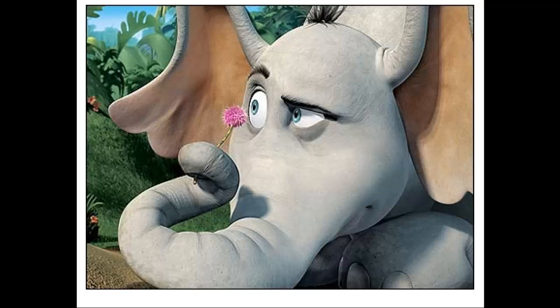And when I talk about scales, I'm talking about the physical rulers, the three-sided scales that are set up for engineering and architectural and mechanical drafting, so that if it says 1/4 inch equals 1 foot, we have a scale, we can lay it on the paper, and we can determine that the length of this room is 35 feet. We can determine square footages and things like that from the computer.